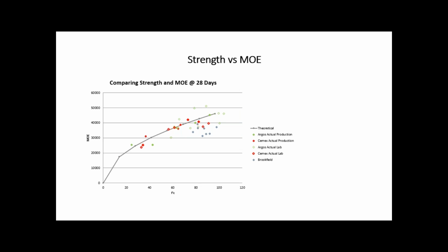It also shows that there is a wild fluctuation, and a major part of it is the aggregate types that you choose and the strength of the aggregates. So it's important to know that, and that's why it's very important to measure.